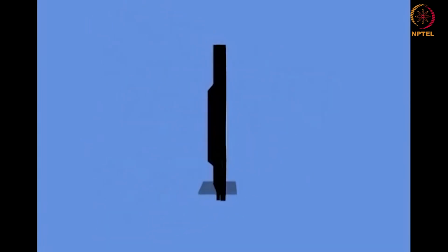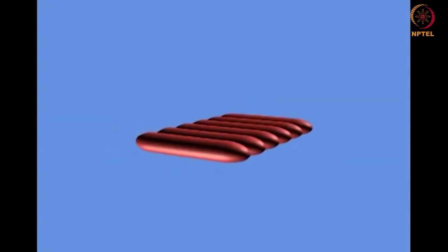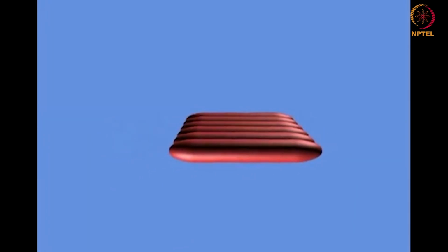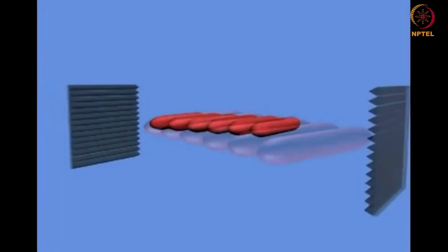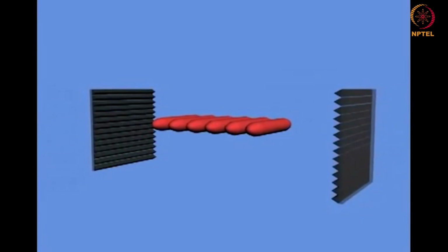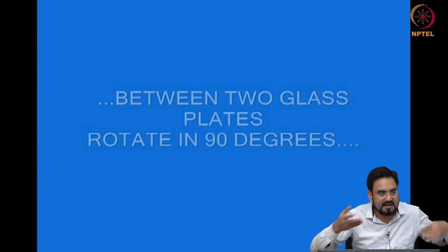In liquid crystals, the molecules are similar to long, drawn-out rods. As with crystalline structures, these molecules exhibit a strictly ordered crystal structure. The ordering of the molecules creates a directional orientation. In most LCD displays, the liquid crystals are embedded between two glass plates rotated by 90 degrees. This formation produces what is known as a twisted nematic LCD. So that's what I was talking about there, 90-degree orientation.